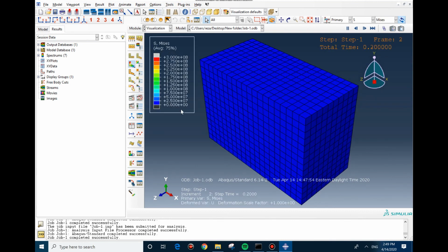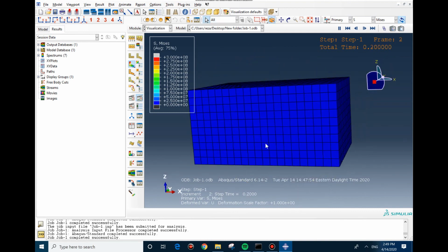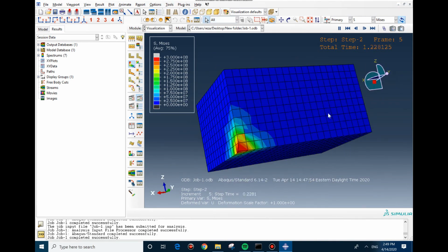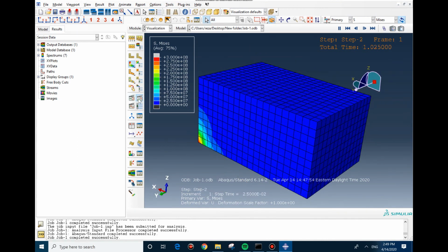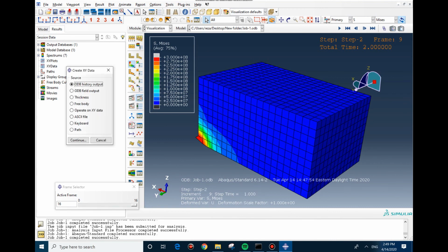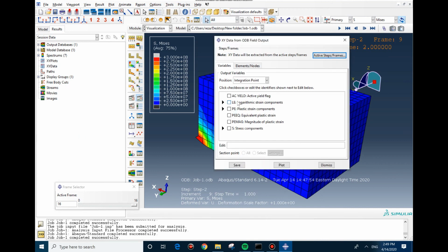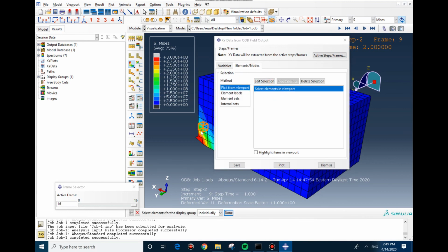First I need to click on here and then I can see the results. It's not a very normal model. I just wanted to show you how Abaqus works. By clicking on here you can see the video, and then by here you can control the video. And also if you want to see the result from a point, you can click on here, and then for example you can go centroid, and then for example Mises stress, then you can pick elements.